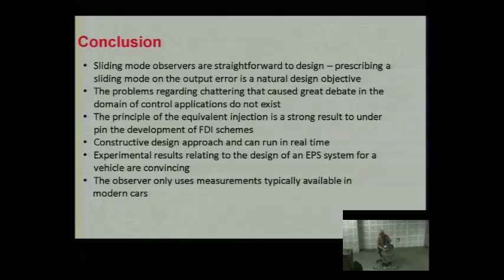We can have higher order sliding modes, where for a second order sliding mode, we try and make S and S dot both equal to 0, and the injection signal effectively acts on S double dot. This was a particular second order sliding mode controller, the super twisting algorithm, that we applied here. But that will be at the heart of what we do with the differentiators tomorrow.